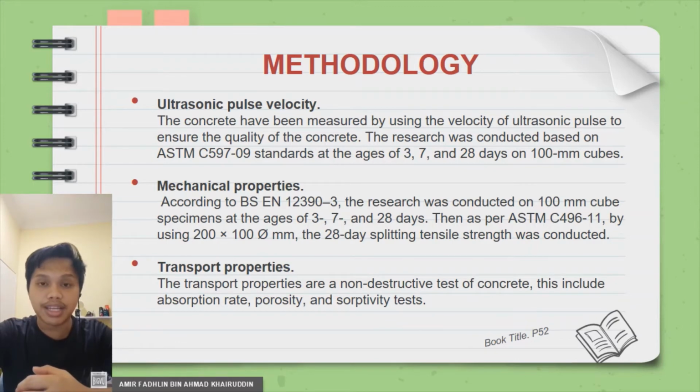Next, we have mechanical properties. According to BS EN 12390-3, the research was conducted on 100 mm cube specimens at the age of 3, 7 and 28 days. Then, as per ASTM C496-11, by using 200 x 100 mm specimens, the 28 days splitting tensile strength was conducted.